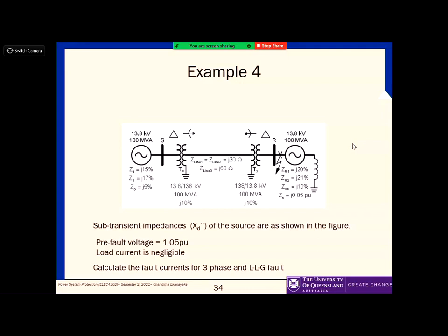And then, if you look at the mathematical expression of this current flow, you will see that during a fault there is a DC component. That DC component is exponentially reducing, which means that after some time you come to the steady state. So usually in a fault you will have 3 different zones: subtransient, transient and steady state.